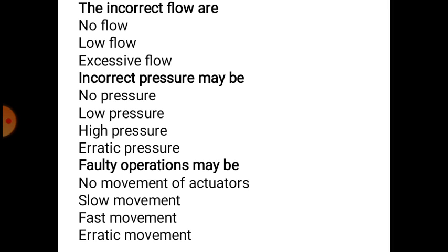And what may be the remedies? Replace dirty filters, replace the part, check for damaged pump, motor, align coupling properly, adjust flow control valve, check the control of valves, replace the part, tighten inlet connections, remove air from the system.